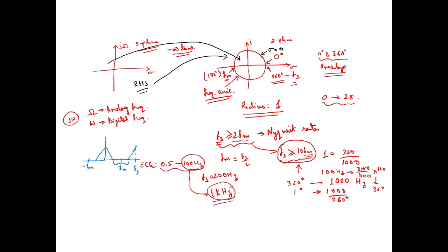Okay. Now let us take the example of an ECG signal. Usually the ECG signal has frequency components varying from 0.5 Hertz to 100 Hertz. However, in some books you may find that it is 120 Hertz. So it doesn't matter, for the sake of simplicity we will go with 100 Hertz. Okay. So as per the Nyquist criteria, what should be the critical Fs? The critical Fs would be 200. Okay, the critical Fs would be 200.